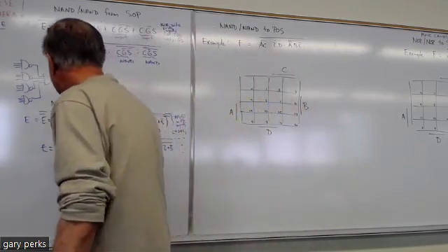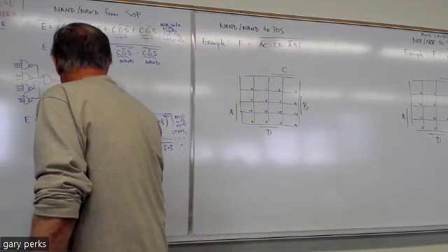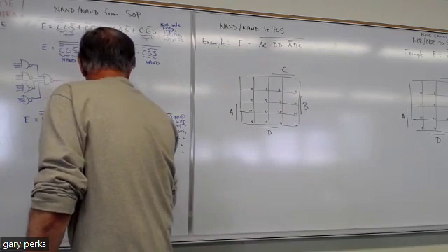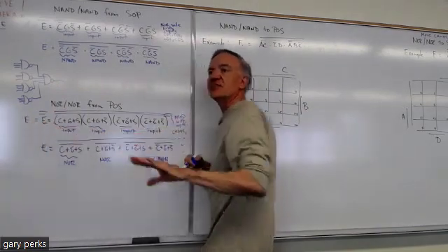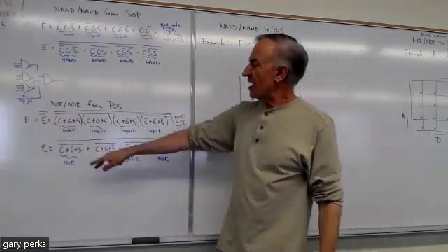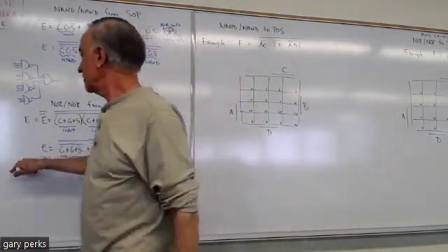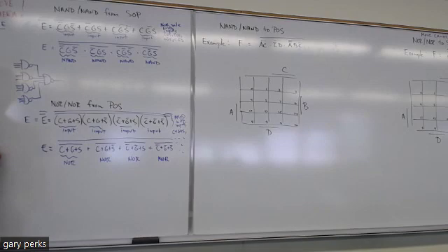Right, so these terms are NOR gates. And then those NOR gates are ORed together, the whole thing inverted. So you see now we have all NOR gates, right? Because each term is a NOR gate. And then we have a single NOR gate that all these feed into.